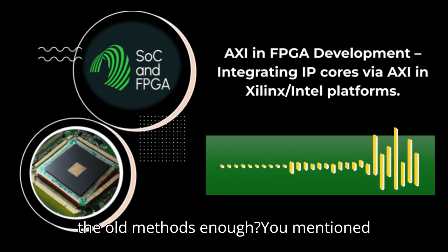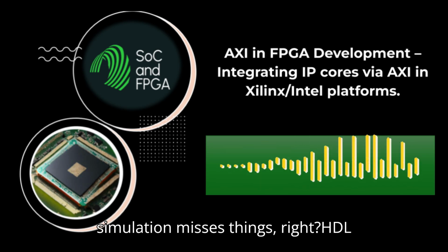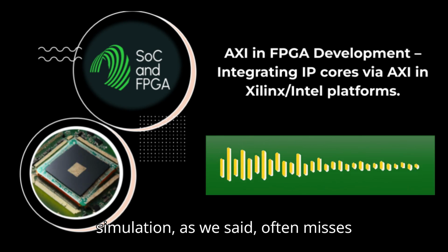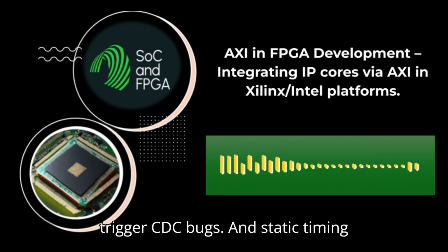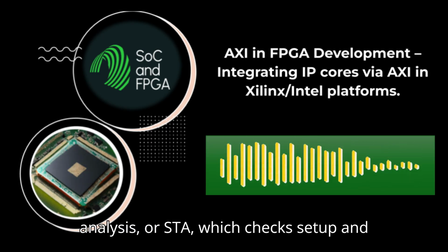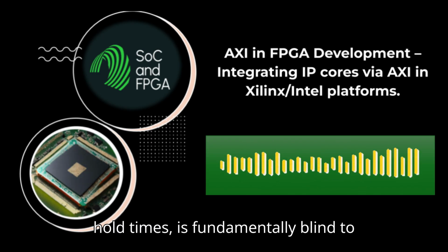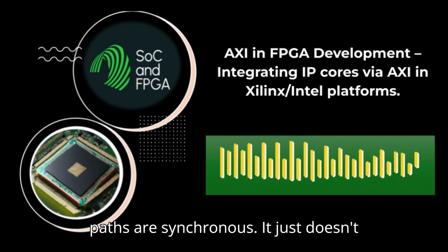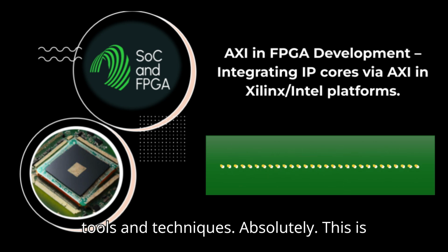And why aren't the old methods enough? You mentioned simulation misses things. Right. HDL simulation, as we said, often misses those rare asynchronous events that trigger CDC bugs. And static timing analysis, or STA, which checks setup and hold times, is fundamentally blind to asynchronous CDC because it assumes all paths are synchronous. It just doesn't see the problem. So you need specialized tools and techniques.